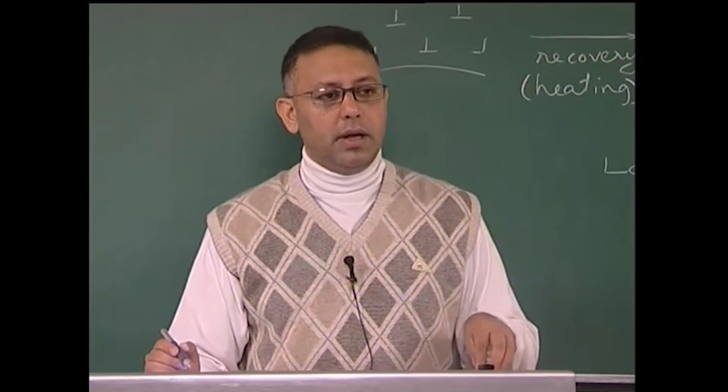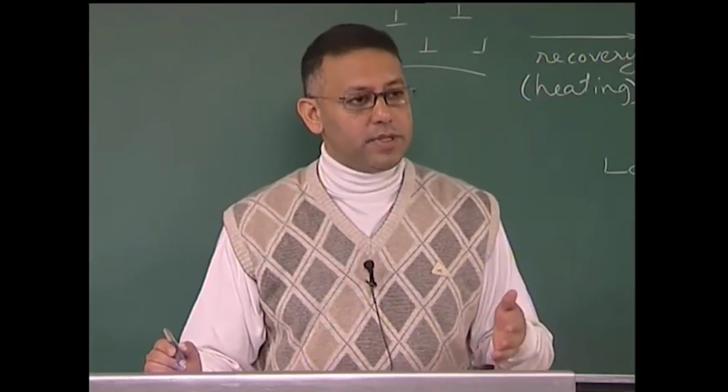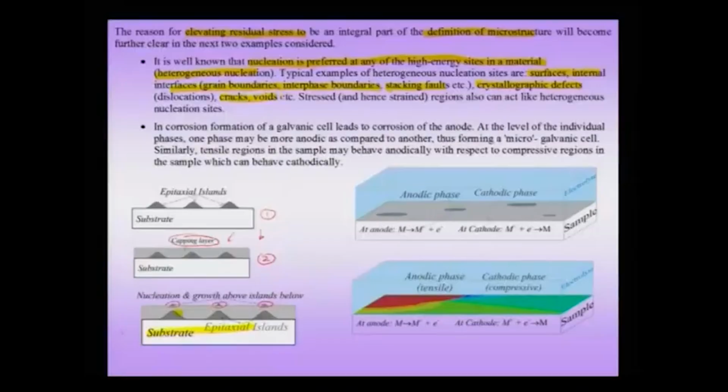That implies that they have a role very similar to that of a defect or of a phase present in a material. Like we see that we could have a second phase, or the interface of a second phase, which could act like a nucleating phase, or a dislocation could act like a heterogeneous nucleating site. Here strain, originating from epitaxial stresses, is the origin of heterogeneous nucleation, and therefore I would want to consider stress or residual stresses part of the definition of a microstructure, like defects and phases and phase distribution.